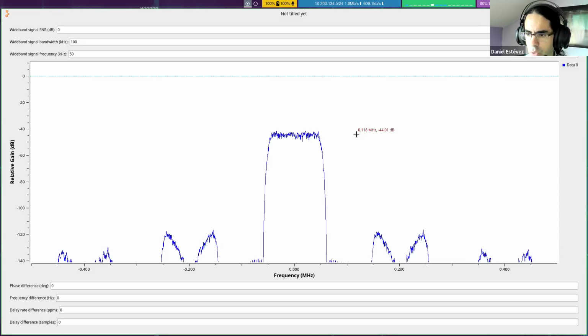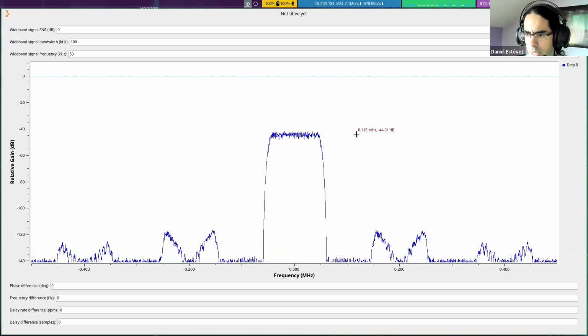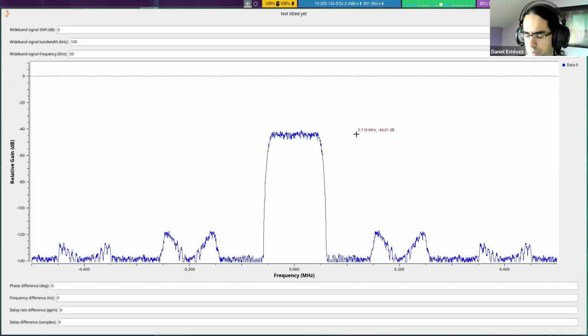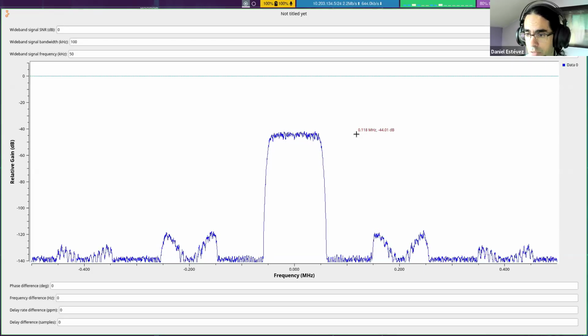And one of the effects we already know, the receivers have a noise floor. That's both noise from the environment, so a part of the contribution to that noise is the cosmic microwave background, which is always, no matter where you point in the sky, you will see the microwave background. It can also be, depending on the frequency and the characteristics of the antenna, galactic noise, it can be ground noise, it can be human-made radio frequency interference.